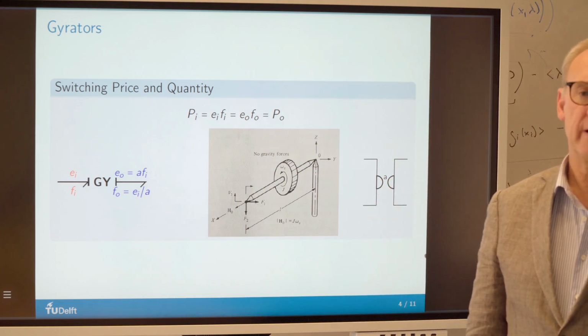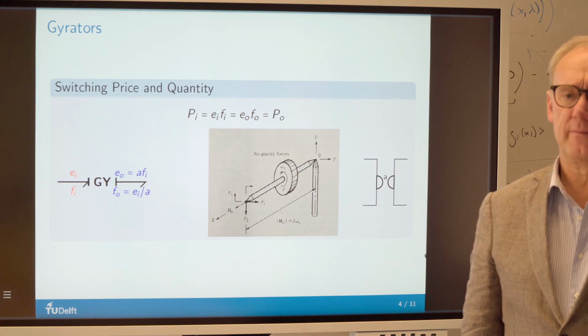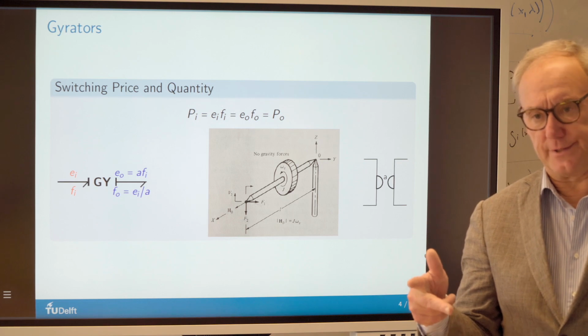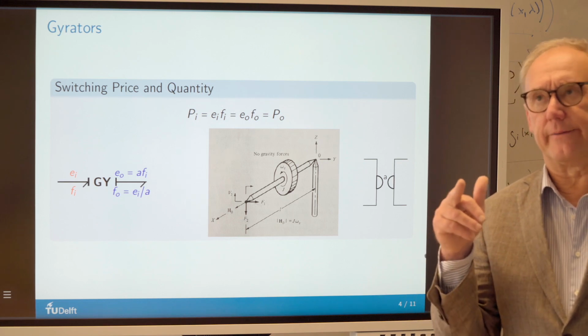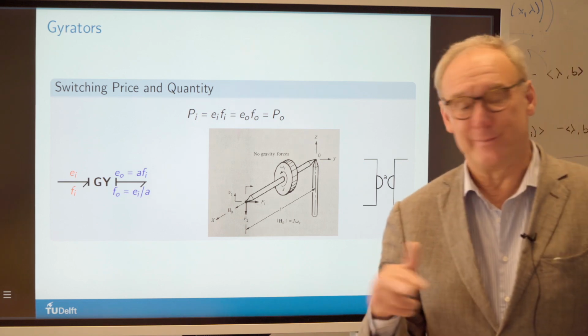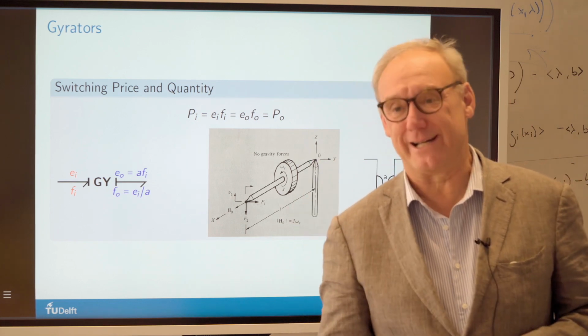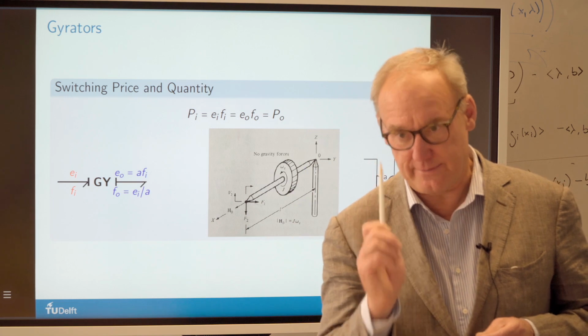No, that is correct. You know why that's correct? Because a gyrator is a reflection and a transformer is a rotation in the space, and you can make a rotation out of two reflections, whereas you can't make a reflection out of a rotation. That's the mathematical basis of this. So this is correct.